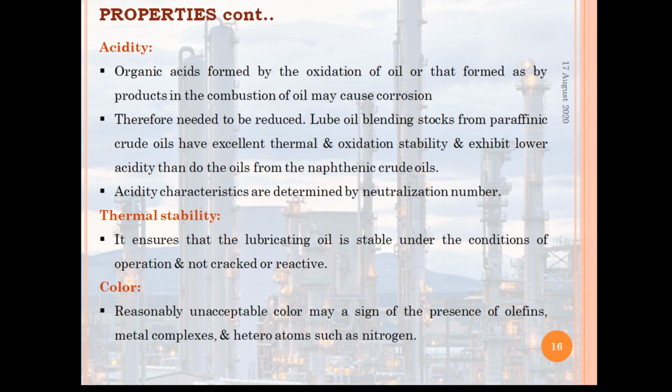If a lube oil's color changes, this change is unacceptable, because it may be a sign of the presence of olefins, which are undesired products with high oxidation tendency, and also metal complexes and heteroatoms such as nitrogen.